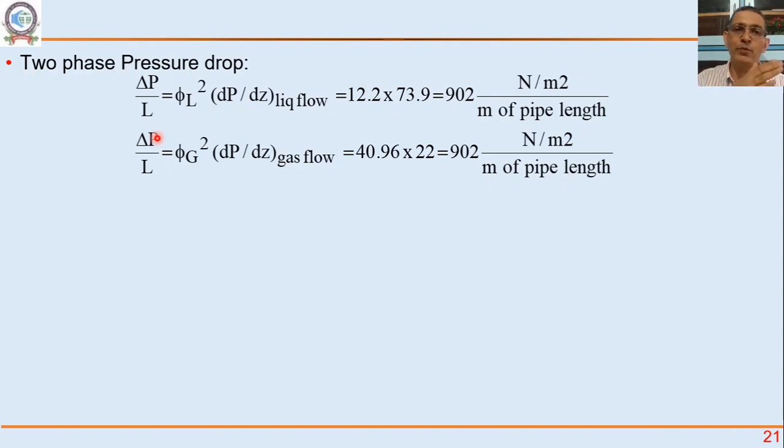what you have transported in the pipeline is a crude oil liquid and a small amount of gas that goes through the pipeline. So the gas is typically methane, hydrogen, ethane. Those are lower molecular weight compounds. And this two-phase flow is therefore very important. We need to estimate pressure drop in that two-phase flow.